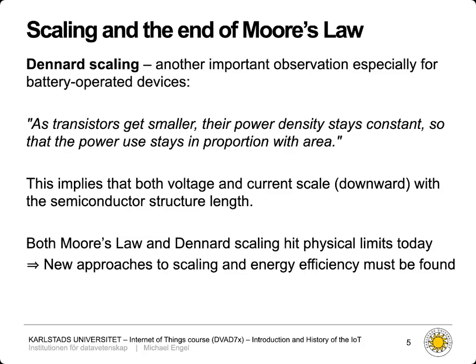power consumption. Now, the problem is that there's another source of power consumption, which is the so-called static power consumption or leak currents. So these are all the currents that flow where you don't want them to flow, but you can't avoid it because you can't build a perfect insulator on chip. So this static power consumption was usually very low compared to the dynamic power consumption that was behaving according to Dennard scaling. But in modern circuits, actually static power consumption is the more significant part, and static power consumption is not decreasing in the same way with Dennard scaling.